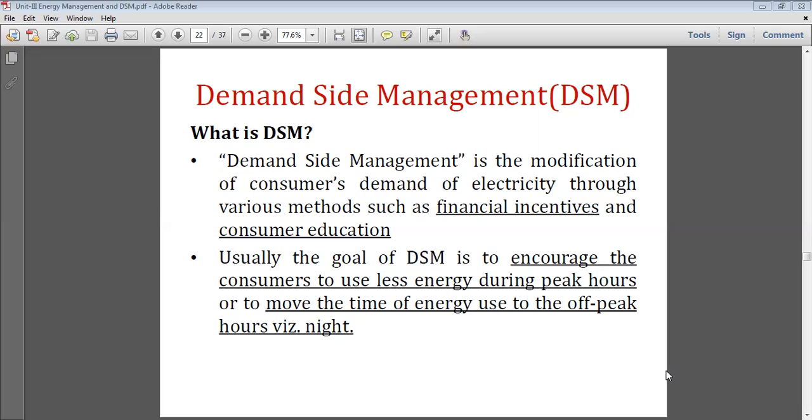So we teach the industries that they should avoid maximum load during the peak period, and shift some of the less priority loads or less priority feeders, or maintain some stock, so that they run their plant 24 hours, so as to keep the load curve as flat as possible.